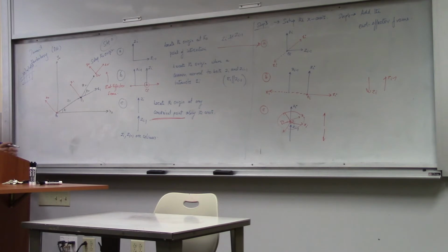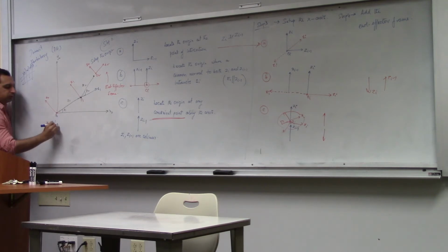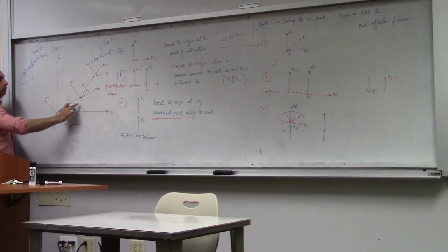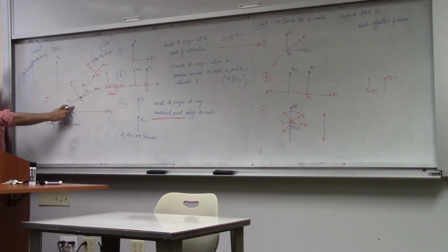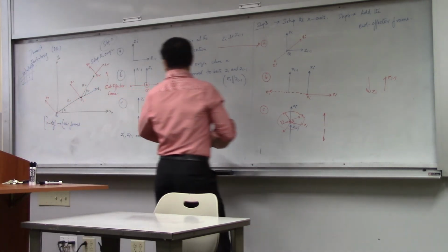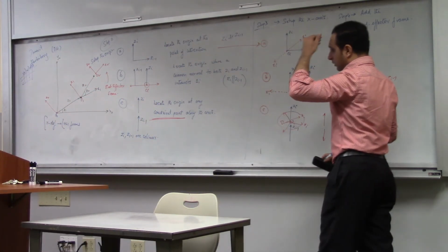Alright. So if you have an n degree of freedom manipulator, an n DOF manipulator, the number of frames will be n plus 1, because you start from the origin and you go up till n. So 0, 1, 2. This is only a 2 degree of freedom manipulator. The first frame is the global reference frame, and you end up till the end effector frame. So you have n plus 1 frames in the case of an n degree manipulator. Alright, so now we have set up all that we need. It's only a matter of measurement.